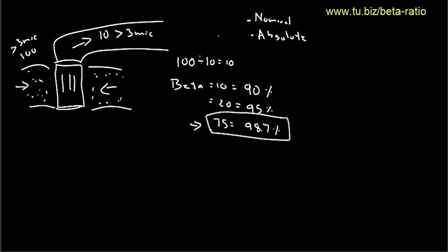Usually, companies can give you a filter and say it's a 3 micron filter element, but it's nominal filtration. What they're saying is it might catch 3 micron particles, but they don't give you a beta ratio.